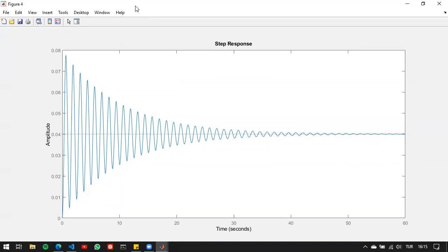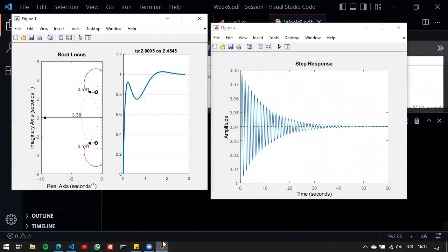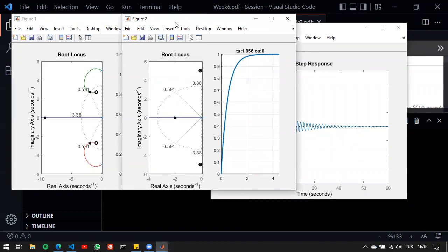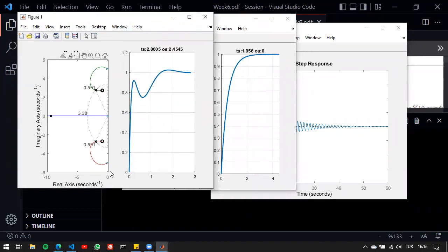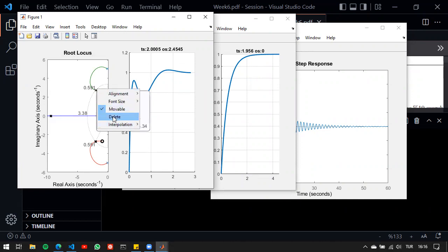Now, this strategy of placing poles and zeros near the j omega axis, or trying to cancel them out, is also not an ordinary method. It is a special filter. If we go ahead and look at the Bode plot of only this pole pair and this zero pair here, what you will see is that this is basically a band stop filter.